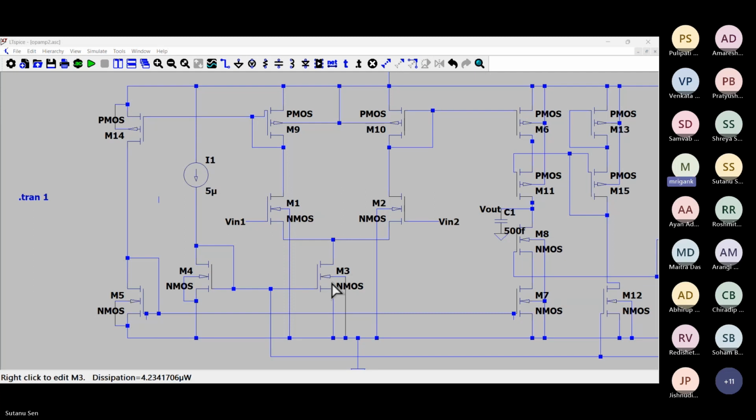As a result, it is creating a difference in the input voltage, so that for the output voltage to be at midpoint, we require a significant difference in the input voltage so that we are in the high gain region. But generally, we have not observed this kind of thing in your Cadence tool. So the way the lambda equations have been modeled may be different over here.